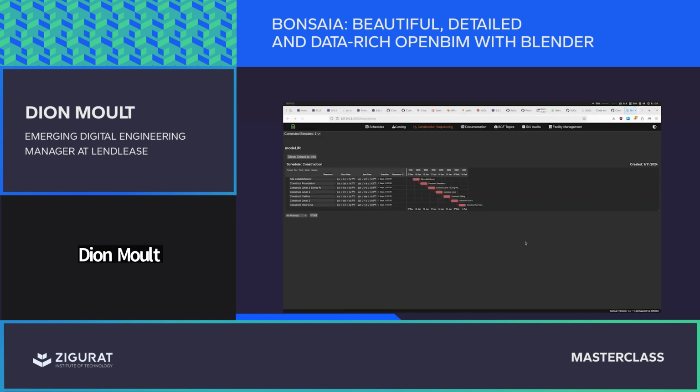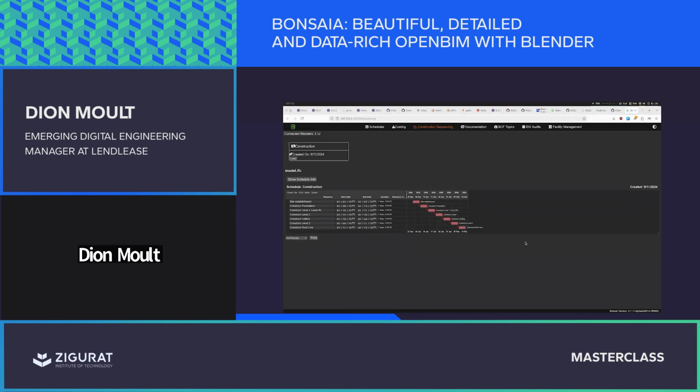You can see this in Gantt chart form over here. This is all live, so I can edit this Gantt chart and it'll show up again in the model. This is all natively in IFC, so IFC will store the tasks, the work schedules, the resources used, and the task time. You can see it's colored in red because it is part of the critical path.